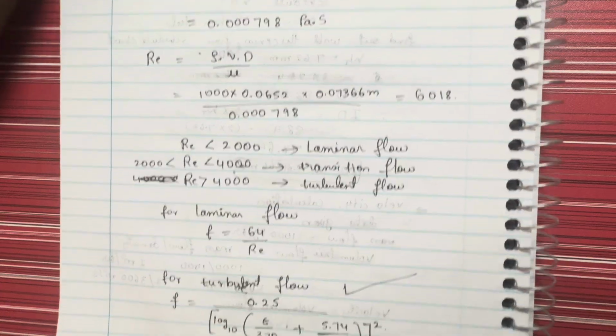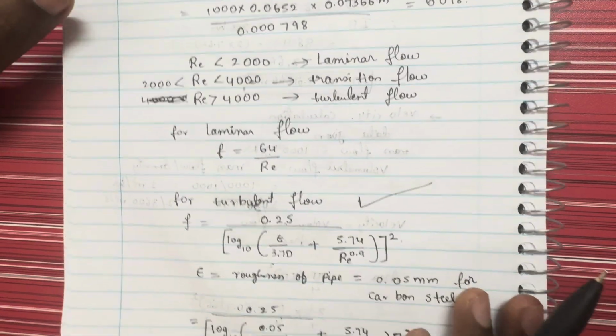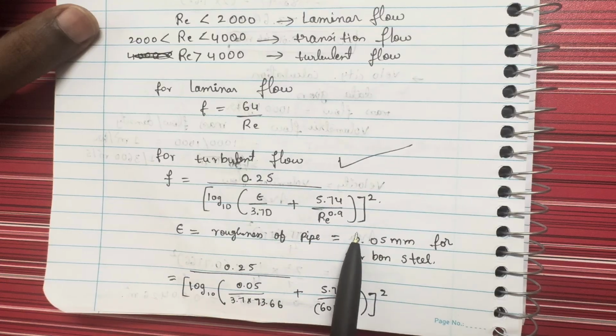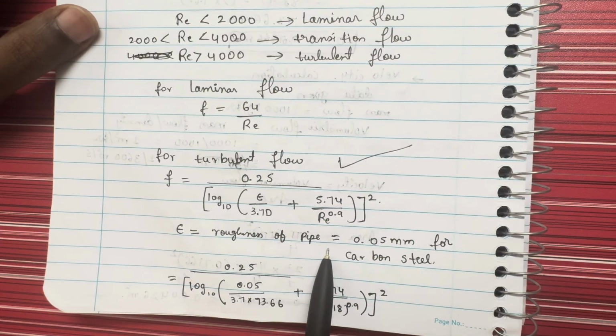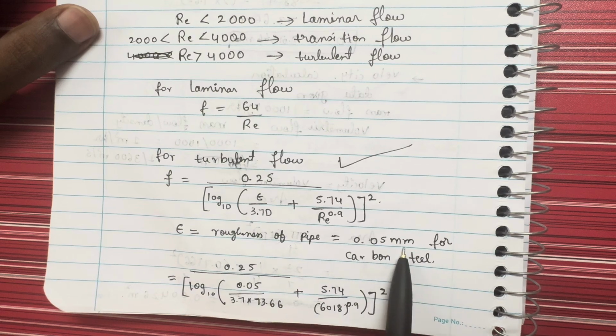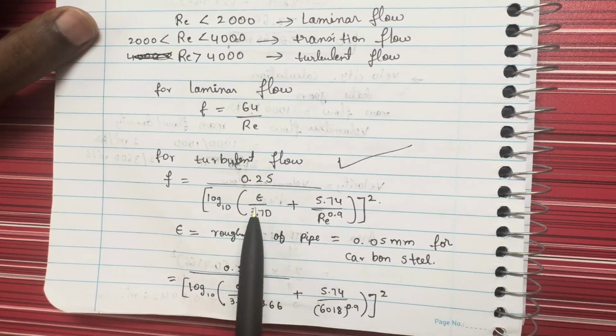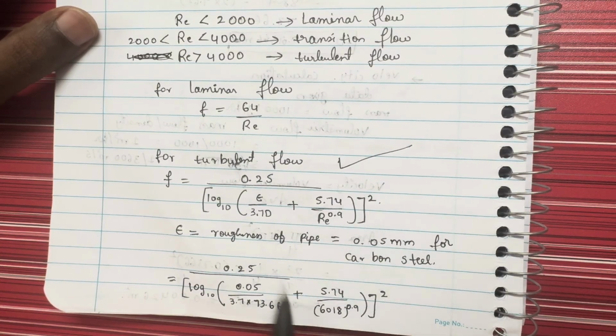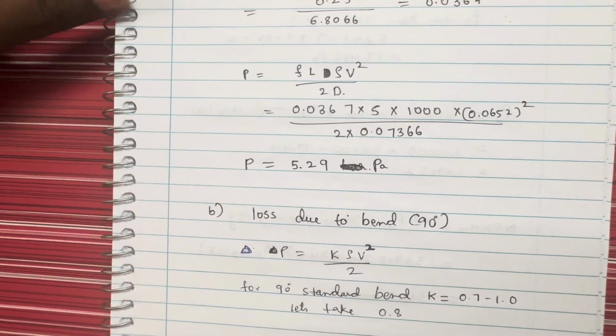Since it is turbulent, for turbulent flow the formula to calculate the friction factor is this. Here epsilon is the roughness of the pipe. For carbon steel, roughness of the pipe is 0.05 mm. If you put all these values here, epsilon, D is diameter, Re is Reynolds number, we will get the friction factor as